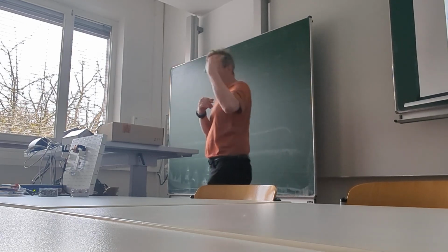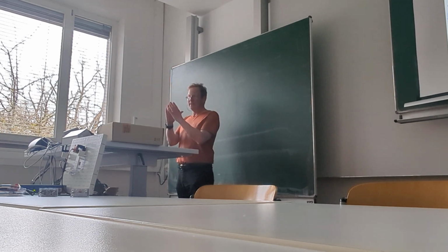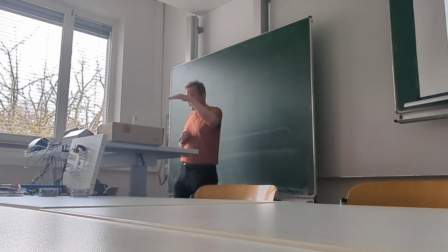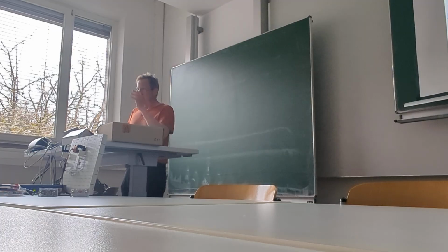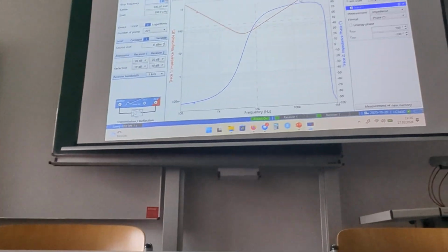So that makes a high resistance. And for slow oscillations, okay, you can get an AC current through a capacitor, but then it's a small current, and that makes a high resistance, or let's say a high impedance, it's called. But this impedance depends on frequencies, and that means it's smaller for higher frequencies. Then we get a minimum, and then the resistance rises again.